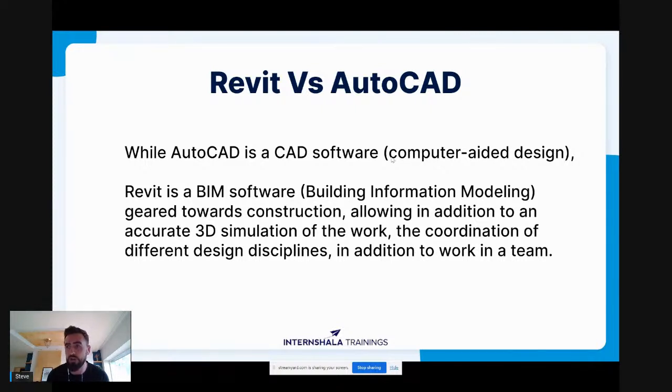With Revit, we have a tool to create walls, offering us the ability to configure the number of layers, type of material, function, thickness, and various other information. In addition, it allows us to extract this very important information and add it into tables and schedules.